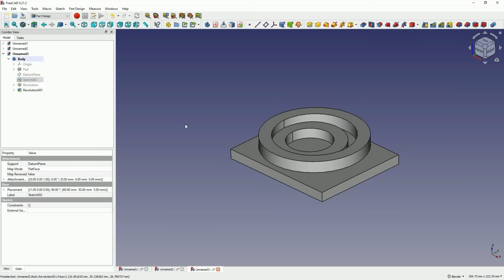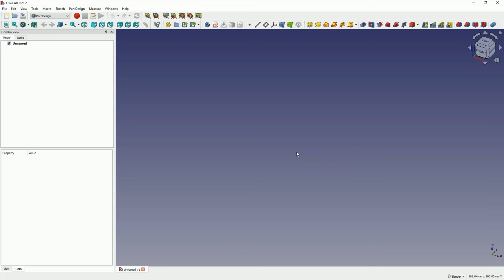Okay, those were some basic pieces of information about creating 3D solids in FreeCAD. Now we will move on to the next example. The next operations worth learning at the initial stage of FreeCAD are linear pattern and circular pattern. We will start with the linear pattern. A linear pattern is something that creates a copy of a selected feature in a specified direction.